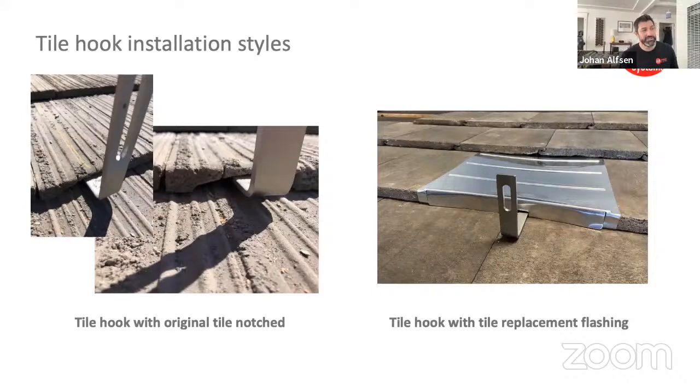So tile hook installation styles. I mentioned grinding the tile. It's a little bit more old school, but this is a good look, and you don't have to look for new tiles or buy replacement tile flashings, but it has its pros and cons. So some installers I've seen just install tile hooks and then put the tiles right on top of it and leave it propped up, and they allow for water intrusion and debris, and that's incorrect. So you want to grind the back of that lug.